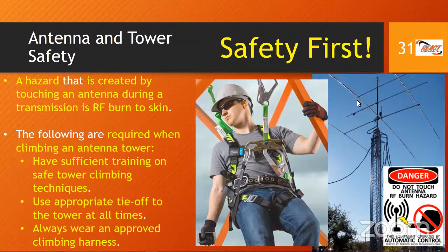If you have to touch that antenna, you can get a pretty nasty RF burn. So getting back to tower safety as well, there are a couple of things that we need to observe if we are doing tower work. We're climbing the tower, we're trying to put up an antenna or take down an antenna or do maintenance to the antenna. We may want to climb the tower, right? So there are a couple of things that we need to know and we should have in place.